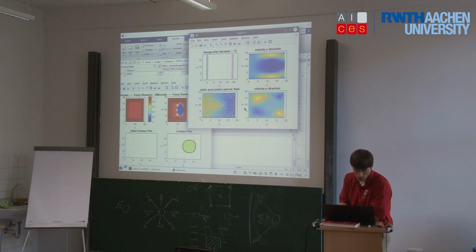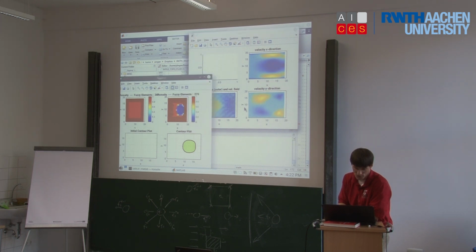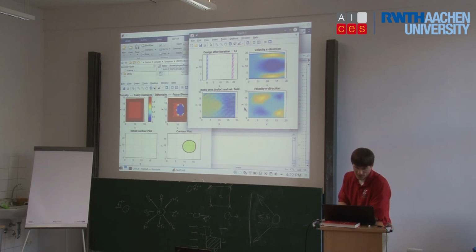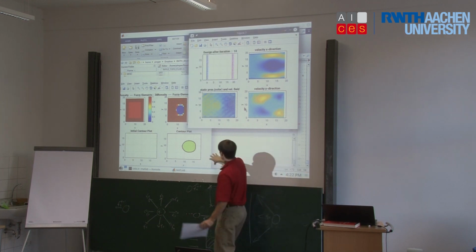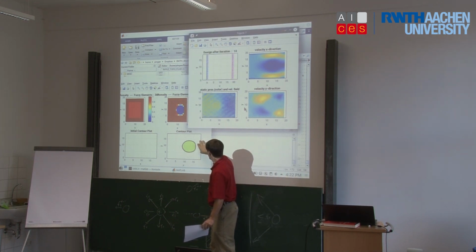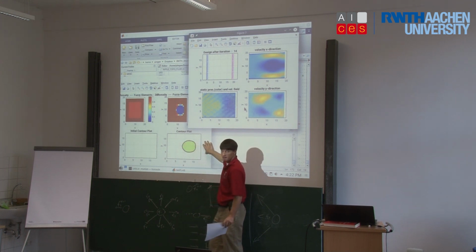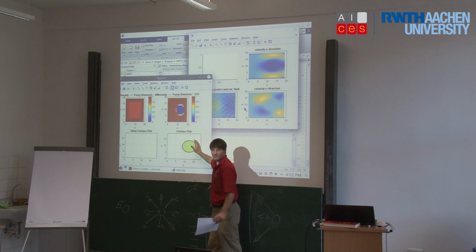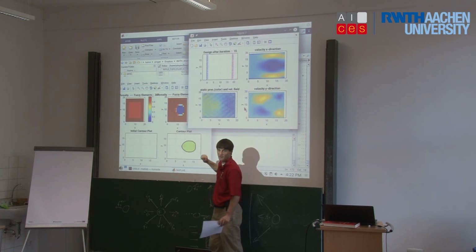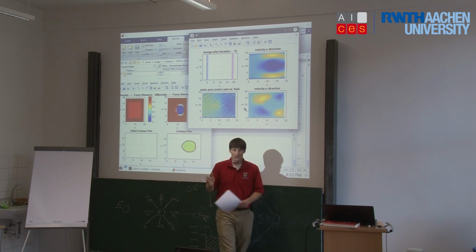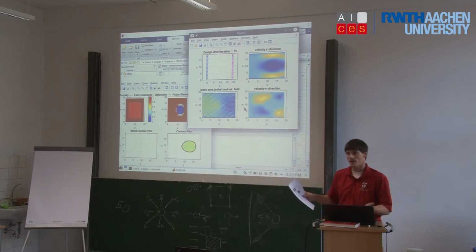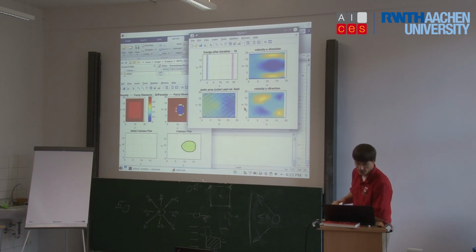Looks like we're actually getting a round ball on this smaller mesh. We'll see if it will make it a little bit flat and elongated. Okay. One thing that you can already notice here is that my design domain is more than likely too close to the exit, and it pushed out the back of the computational domain and wants to sit against the back, so that it doesn't really have time to impact the flow until the flow gets to the outlet. But you can see it starting to elongate a little bit, like an ellipse.